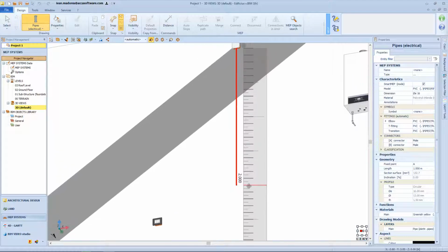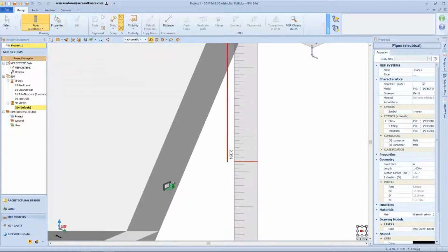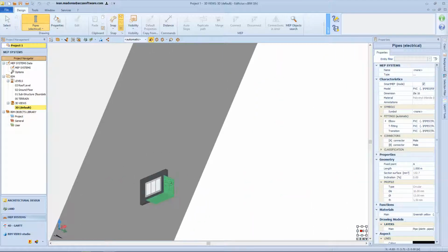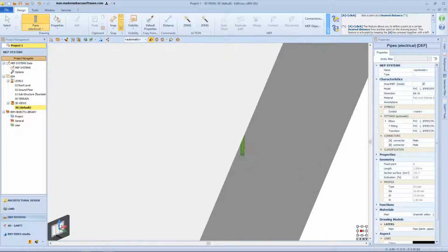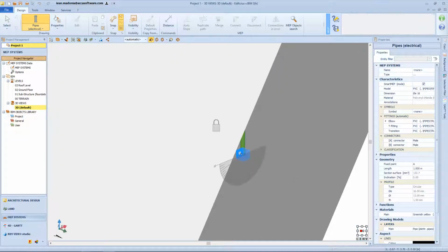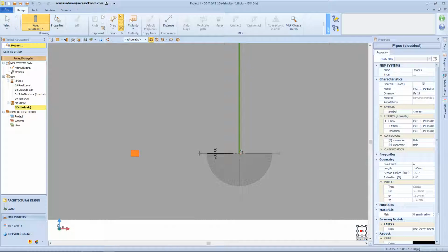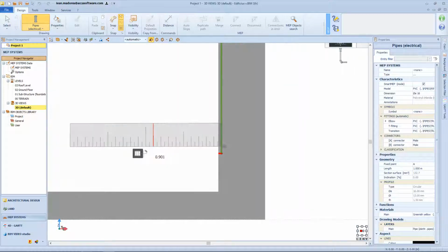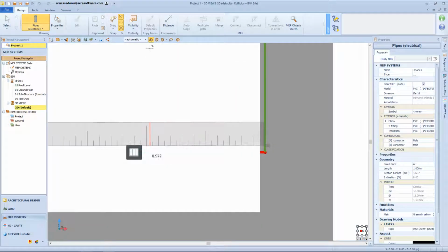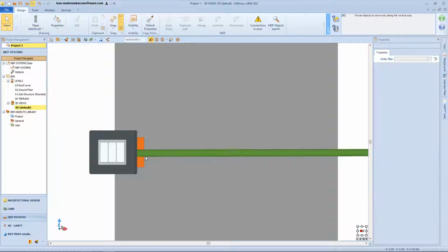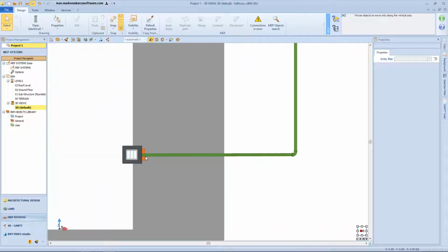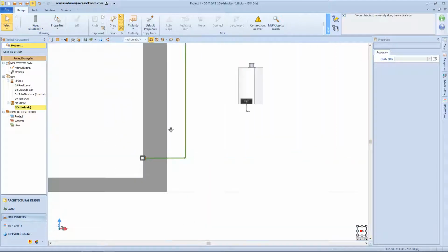The cube allows the user to trace the pipe along one of the planes parallel to its faces and to pass through the starting point chosen for connection. The protractor allows you to define direction and verse in the identified plane. With a click of the mouse, the pipe is fixed along the chosen direction and the ruler appears to define pipe length in a subsequent step. Alternatively, you can trace to another available connection point to link multiple objects together. Also in this context, blue snaps are available to take advantage of reference points or lines on the model.